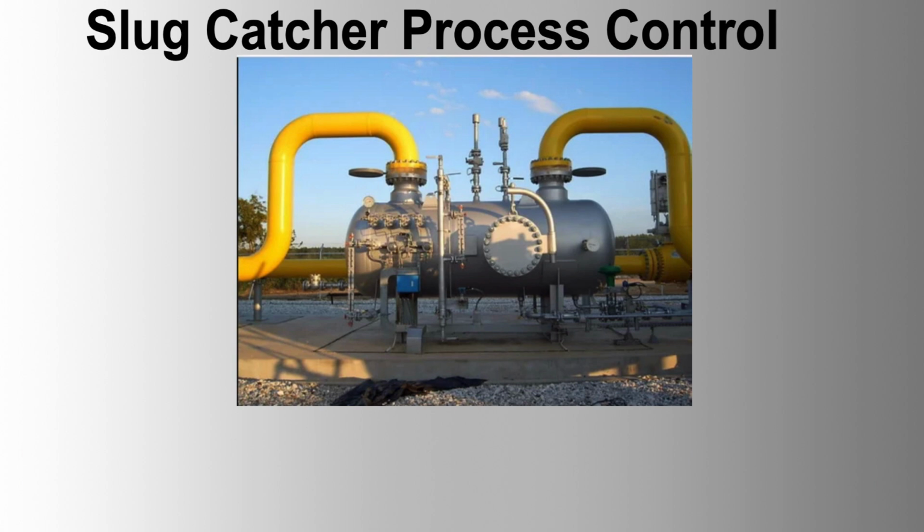Example: if an increase in flow is detected from multiple well clusters, the inlet valves can be adjusted to manage the total incoming flow rate, ensuring the slug catcher operates within its capacity.